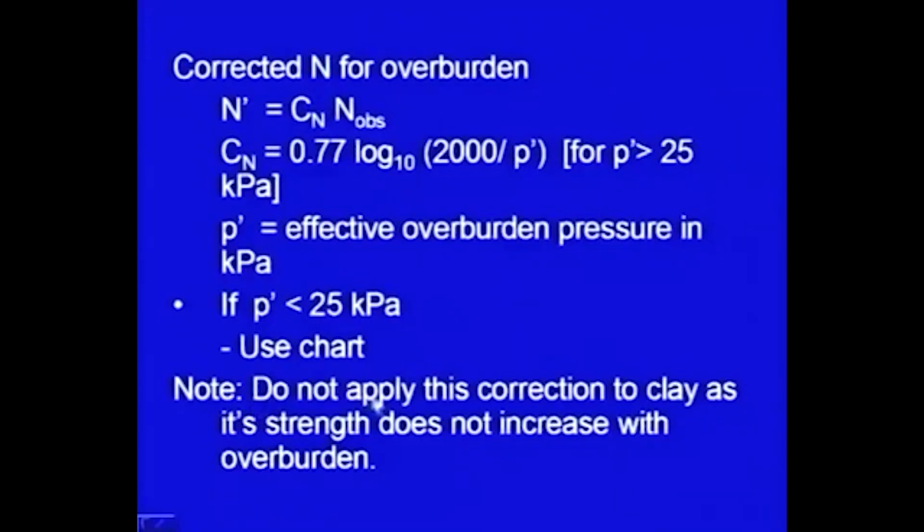Again, do not apply this correction to clay, as its strength does not increase with overburden. This I have already discussed. This correction is applicable for the sandy soils, in which case the strength increases because of the confining stresses.